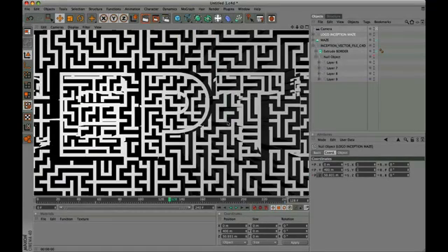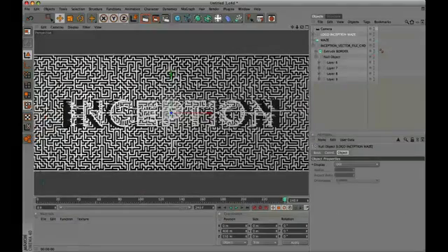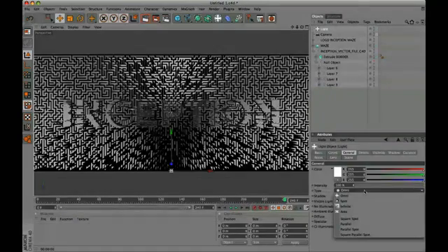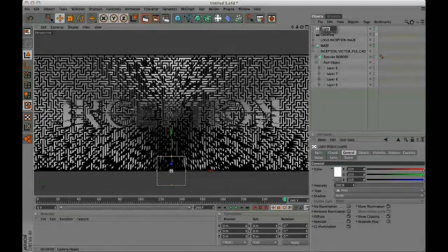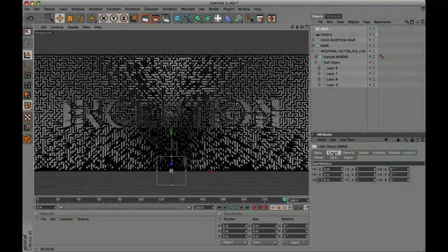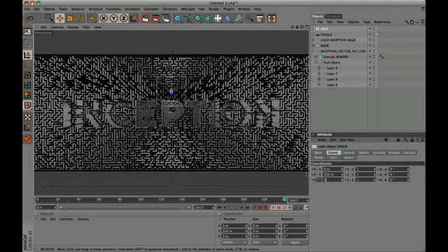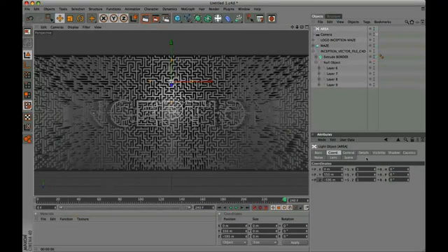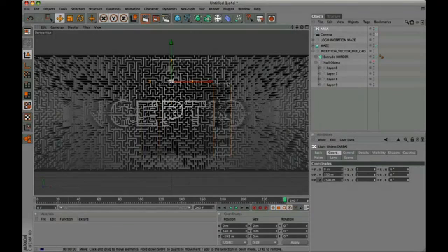View the render. The logo goes off behind the labyrinth. To improve the result, insert the first light, of type area. We set the intensity to 80, and in the coordinates panel, insert the following values: Y 550, Z minus 595. We make a render.